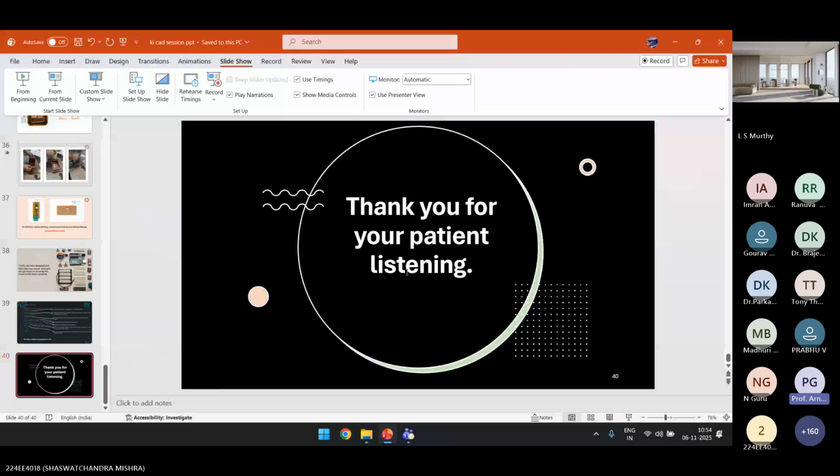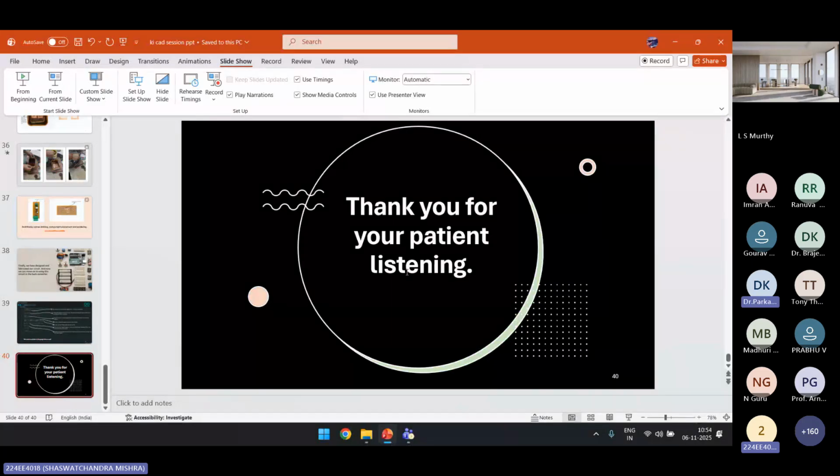Good morning. Nice presentation, sir. I have one doubt. Single layer PCB design or multi-layer, which one is preferable, sir? Actually, multi-layer is preferable, but for multi-layer, we will have to go with PCB manufacturers like JLC PCB. But let's say you are making a prototype, so you'll be having many alterations. Every time you send it to a PCB manufacturer, that won't be cost friendly, and it will take a lot of time because you will send it, then they will reply.